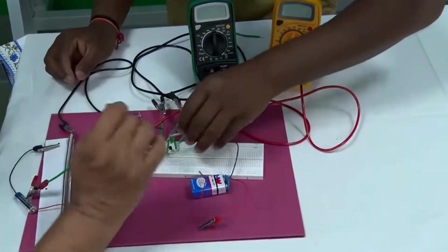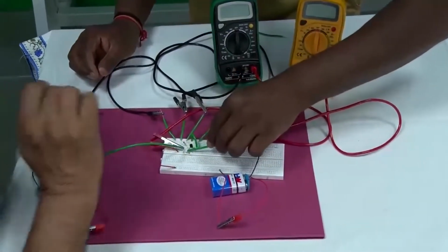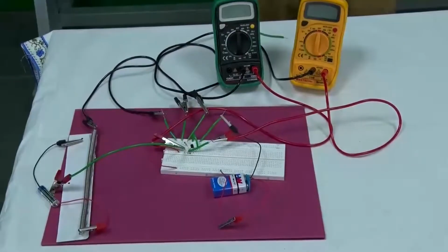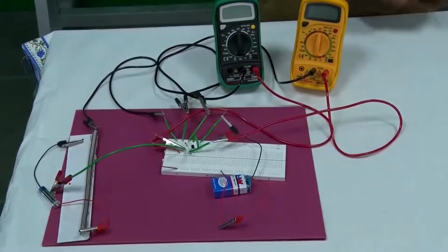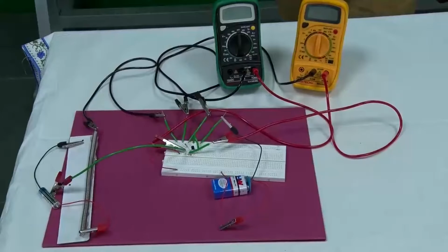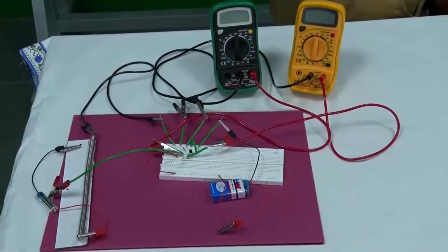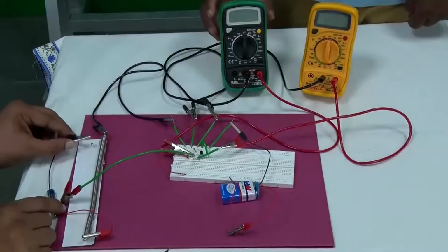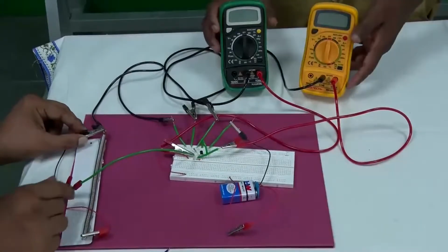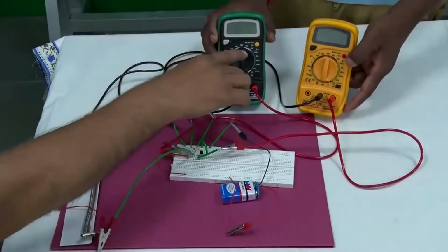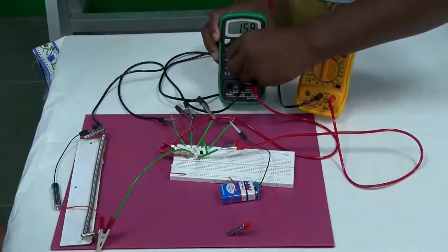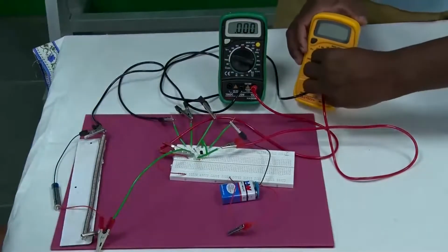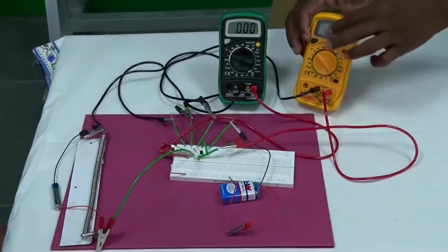And you can connect this thing here, right. So, now it is connected to the collector. Okay. So, the circuit is complete. So, let us start working on this. This 1.5 volt battery I am now connecting, all right, and put this in DC voltage 2 volts range, and the other one output 20 volts range.